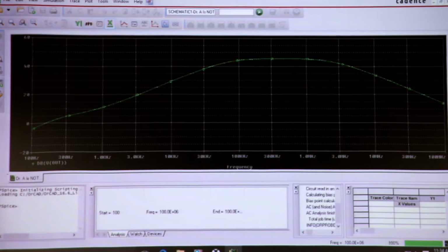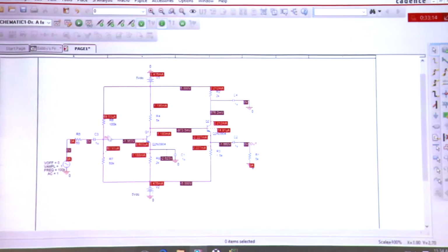It's a good idea. That VN is a good place to illustrate that. You got 2 wires crossing. Yeah. Alright, so a couple of people had a problem with this junction here where you had wires crossing each other instead of actually intersecting. So if you look, there will always be a pink dot. If 2 wires are actually intersecting, you should have a pink dot. So like here, here, here, there's a pink dot.